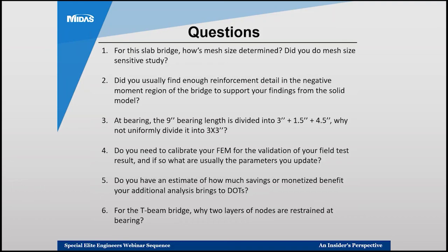But sometimes you can start without modeling the barrier. Then you start seeing things and you think about why I'm not including the barrier, where it's an integral part of the bridge. Now you start introducing modeling the barrier, the diaphragms, and this is basically how refined your model is at the beginning. So if you end up with a very refined model from the beginning, taking everything into account, then you may not need to go back and do anything for your model after that. So I hope this answered your questions.